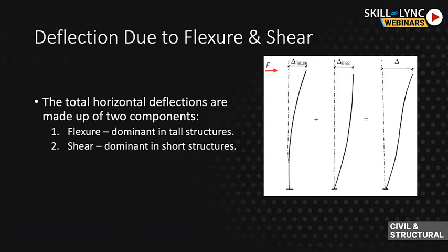So usually the taller your building is, when you're dealing with a high-rise building, the dominant component out of the total deflection will be coming from flexural deflection. The shorter your building is, then most likely it will be governed by shear deflection.